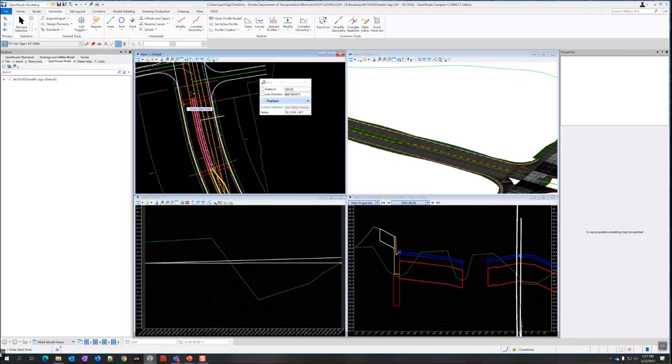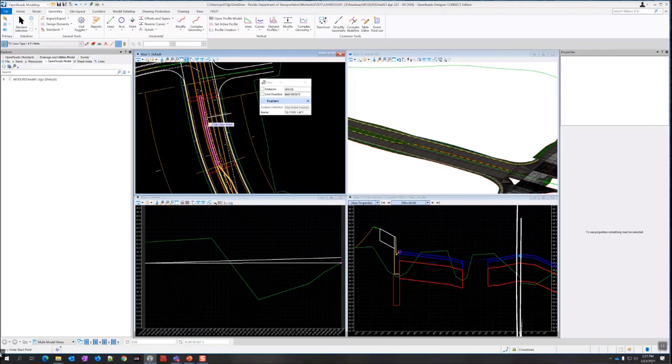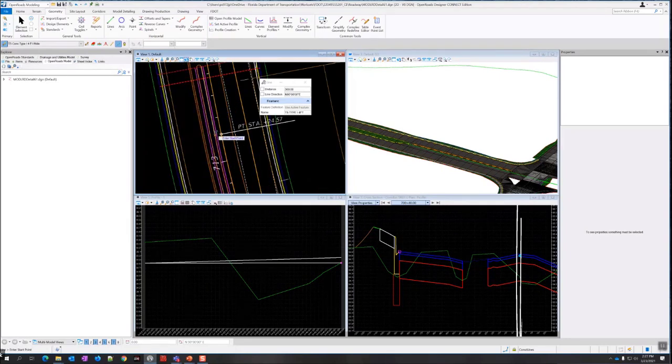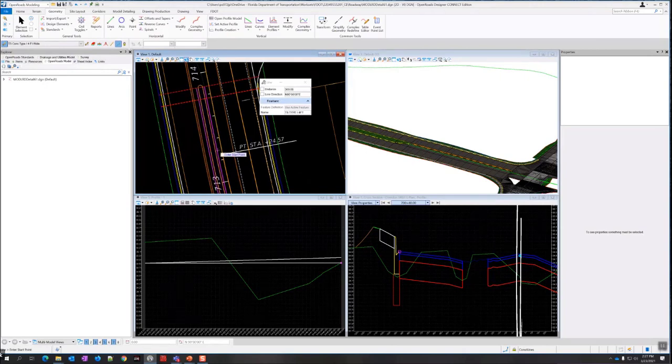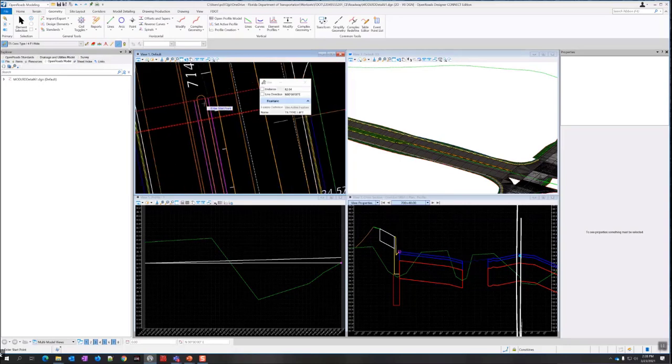That's a good reference here. So this one's a complex. It's going to be 2 pieces. Really, I don't need it all the way down here. So what I'll do is I'll just do this piece here because I only need it for the end. So I'm going to do this one again, going the same way as the corridor, using the lines. So I'm just going to snap it to this line here and snap it right here. Try to make sure it snaps on the line and not something else.